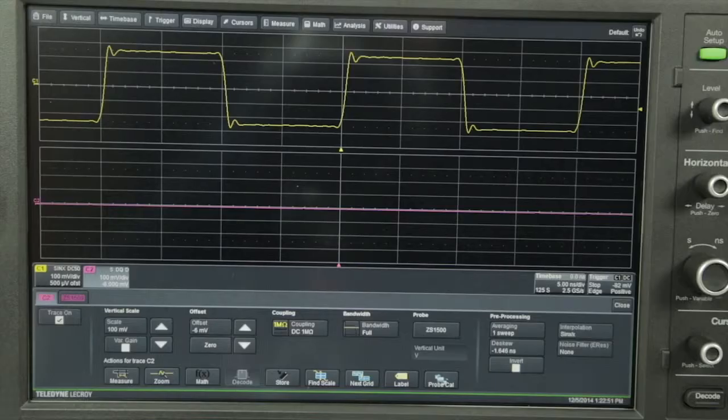Active probes typically offer higher overall impedance, which presents high resistance to DC voltages and low frequency signals, and low capacitance to high frequency signals. Active probes have high resistance at the probe tip, but terminate into a 50 ohm input of the oscilloscope.